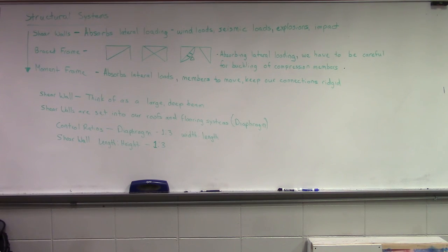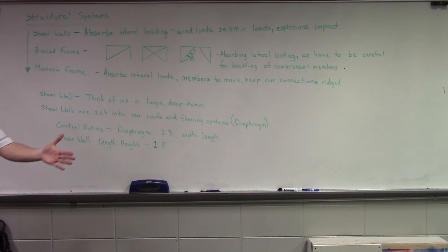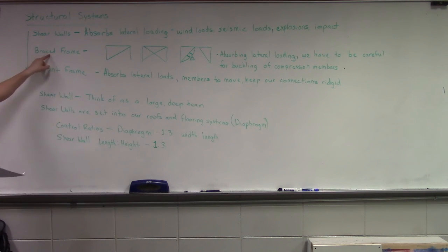Think back to the Boy Scouts of America building that we went to last semester. Remember when they talked about the CEO's office that they have? They were doing brace frames in that bay where that office was going to be. And because of his window, they were no longer able to brace frame. They had to switch to a moment frame for that portion. Okay, so we can mix and match any of these three depending on what it is that we're going to do. Okay, so the moment frame from a design standpoint, even though it's not as stiff,